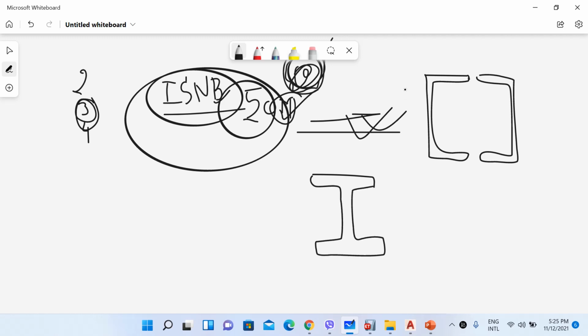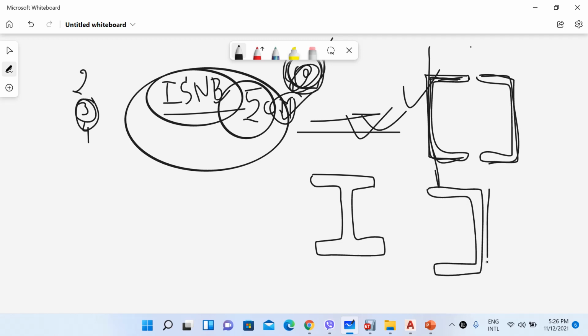Now you may ask, why don't we use a single channel section, or a comparatively larger channel section? Why do we not use only one channel section for the column? Because you can see that this channel section is not symmetrical about the y-axis. So to make our column section symmetrical, we create this built-up section by using two ISMC sections, or two channel sections, placed front to front, or you can also place them back to back in this way.